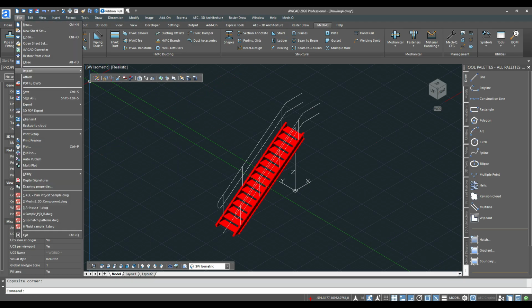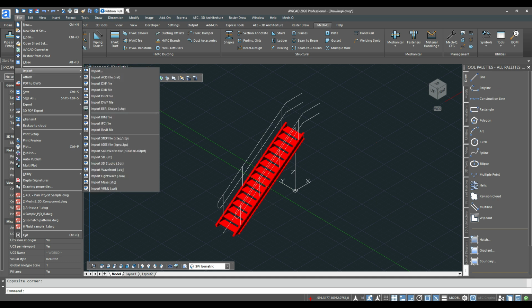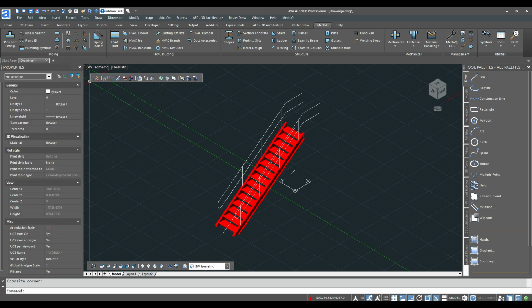While we're there, file import. Where's my import? Check this out. Import from ACES, which is AutoCAD type stuff, STEP, even Revit. Okay, Revit's cool. If you're collaborating with other disciplines, architects or designers probably have a Revit file somewhere. You can use that to collaborate. I would just lock the layers and start drawing on top of that. There are some examples we can show you on that as well. There's STEP I just import, even SolidWorks. All right, so you're geared for importing and exporting.